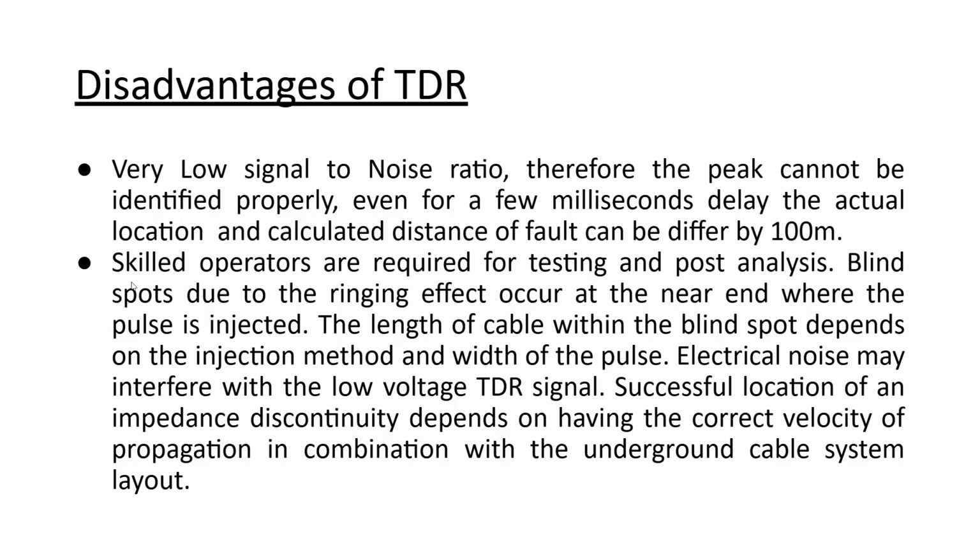Then the second disadvantage mentioned here is that skilled operators are required for testing and post analysis, because we will see just after a few slides how complicated it is when joints are present. So an operator who has the knowledge of how the reflections will occur is required to analyze the location of the fault and any problem within the insulation.